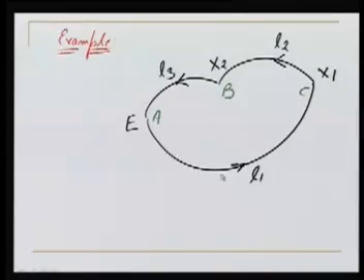From A, we found L1. L1 is the difference between RL of A and C. Using that, we can find the value of X1. X1 is RL of C. Now, from X1, I went to B. The difference in RL between C and B is L2. Using this route, I can determine the RL of B also. But again from B, we went back to A. So now the RL of B can also be determined directly by taking into account this L3. It's a very simple thing.